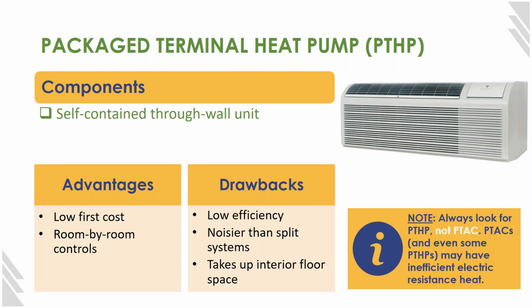What you don't want to do is air seal the unit itself to the wall, because if you ever have to replace it or take it out... I think the sleeve is what you generally want to air seal. But I would say talk to the manufacturer. That's the main thing. Yep, great point.